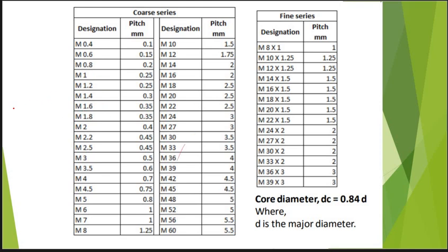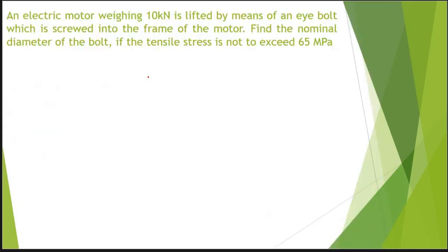Suppose we have calculated and determined the bolt size as 1.1 mm, we have to check in the table whether such a bolt is available, a bolt having nominal diameter 1.1 mm. No. After 1, the value is 1.2. So we will take the bolt size as 1.2 mm. So this table is used for selecting bolts as per the standard.